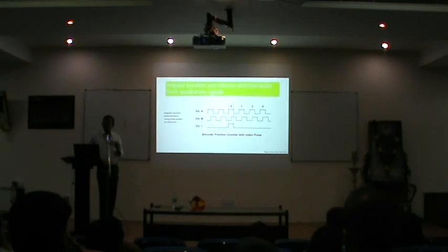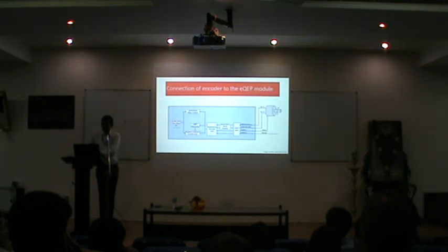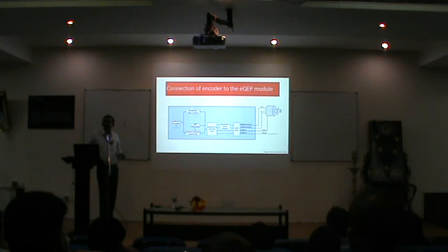To determine all these things, once again, we have a provision in our C2000 microcontroller in the form of QEP modules. You just take an encoder, feed the encoder pulses to the QEP module. The QEP module will do the rest of the job. See how things are getting simplified.